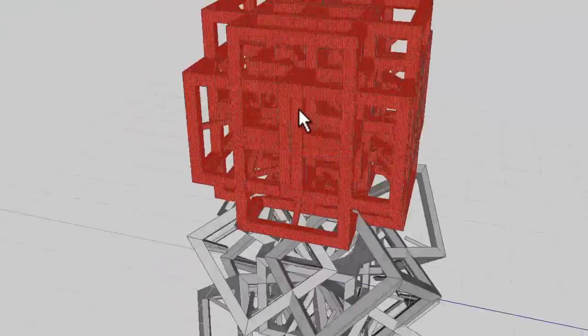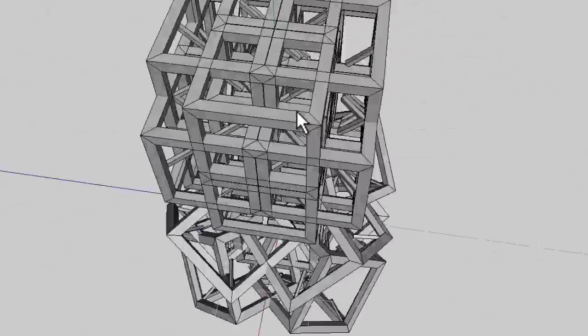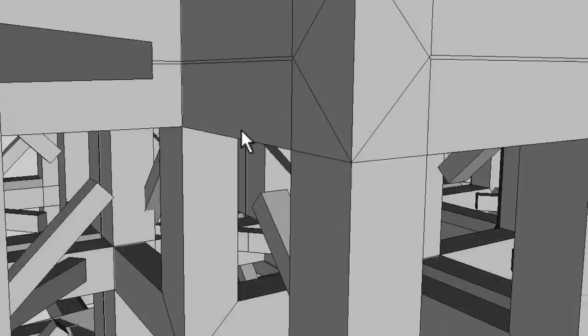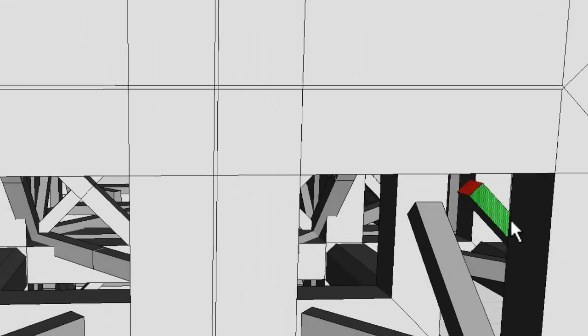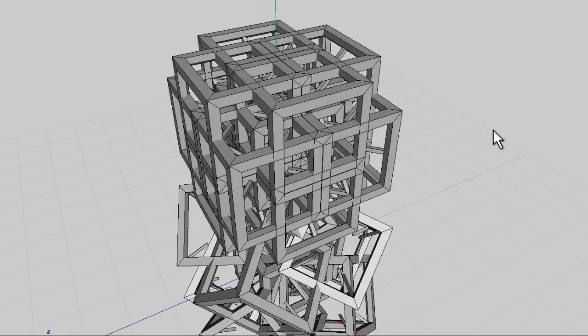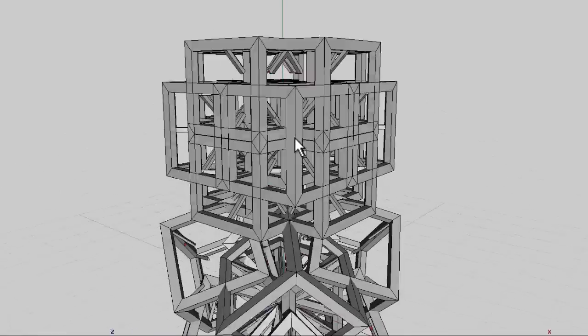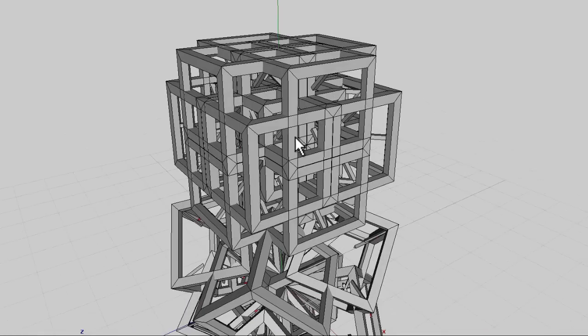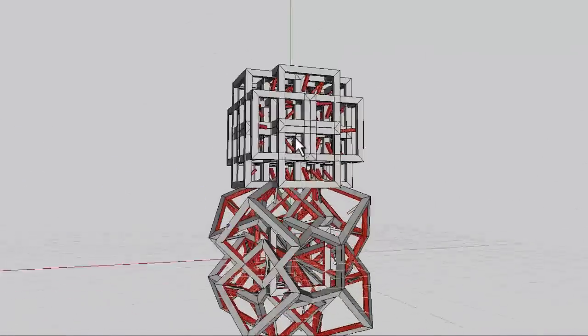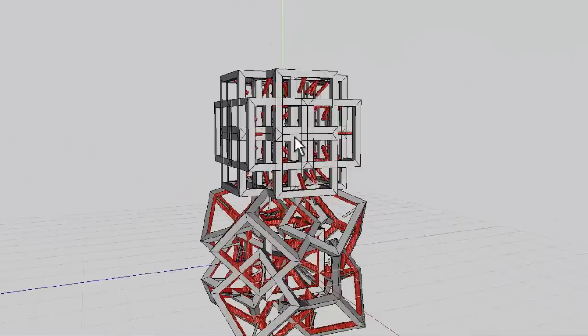Now I just need to drop one into the other, but before I do that, I've got all these little sticks sticking out inside the object that I use to generate the shape. So what I need to do is select a face on the inside of that, press identical so all those faces are selected, and then I can press plus, and whoops, I've forgotten about the fact that I've got the other faces selected in the other one. I should have done the scaling afterwards.